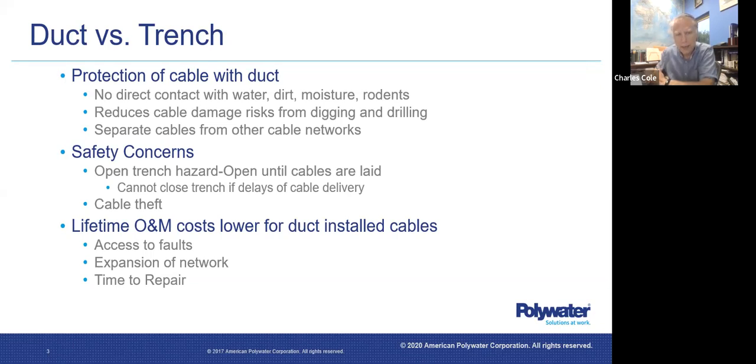There are safety concerns as well. Open trench is a hazard. You have to open the trench, and you have to keep that trench open until cables are laid. This is difficult when, let's say, cable delivery has been delayed and the trench has already been opened up. You've got pedestrian traffic that might be in danger if they fall into the trench.